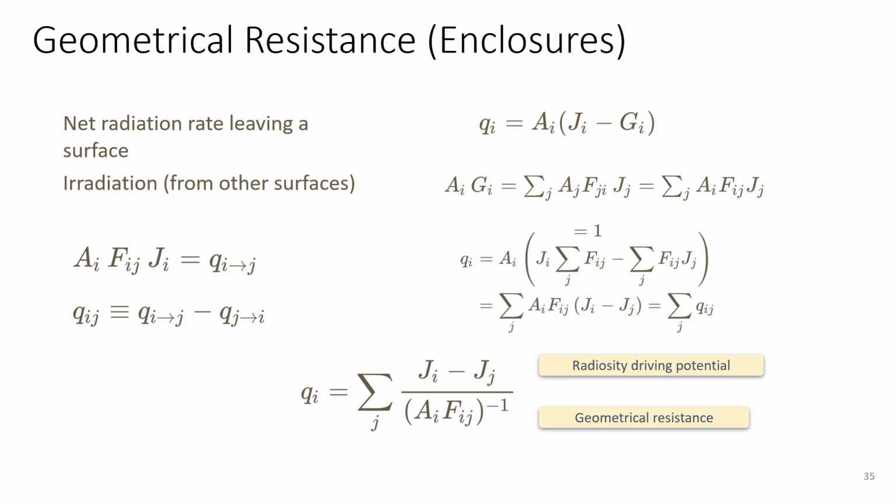So similarly, if we have multiple sources of geometrical resistance, that is, different kinds of surfaces, then the overall resistance and the overall heat transfer rate we can just write using this summation, that is, J1 minus J2 upon this summation. This we will see once we solve the numericals.